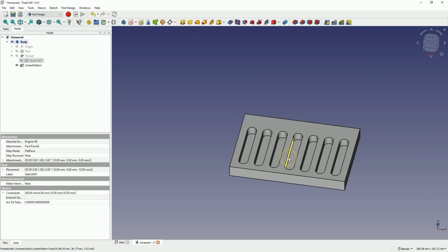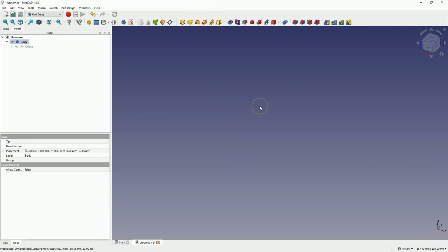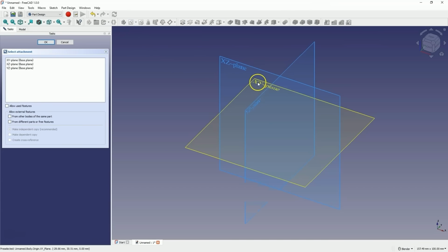This operation can also be useful in creating 3D models and in some cases can significantly speed up and simplify 3D modeling. The next operation in the group of operations where we create additional copies of a selected feature is the circular pattern operation. This operation creates additional copies of the selected feature around a circle, and now we will create a sample model. Choose to create a sketch and select the XY plane as the sketch plane.